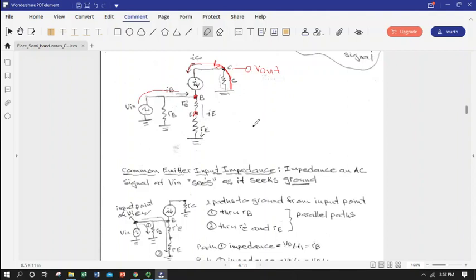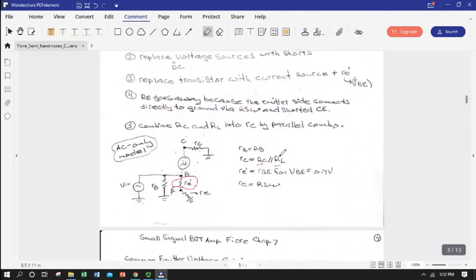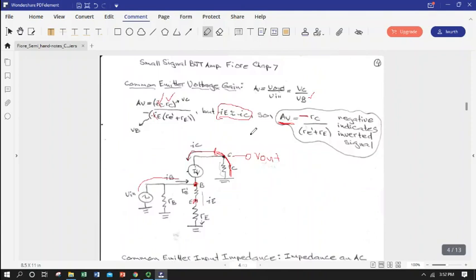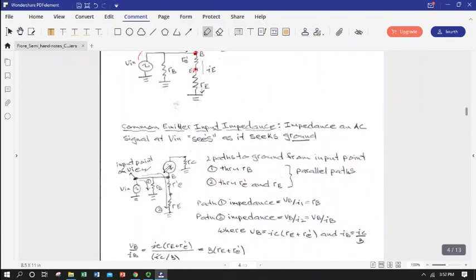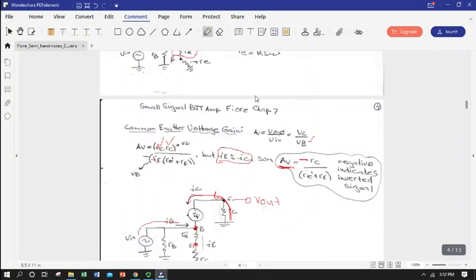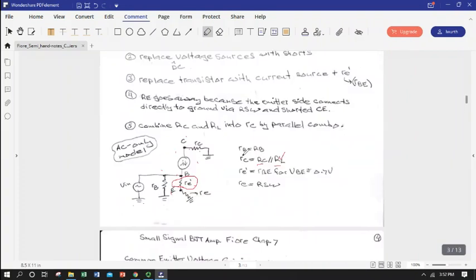We have a loaded output. The very fact that we have already combined a load resistor here with our collector bias resistor means we've got a loaded circuit. So that's important to know how much that is. So we've kind of already rolled the output impedance loading effects into this definition of voltage gain, simply because this R little c has already put the load resistor in parallel.